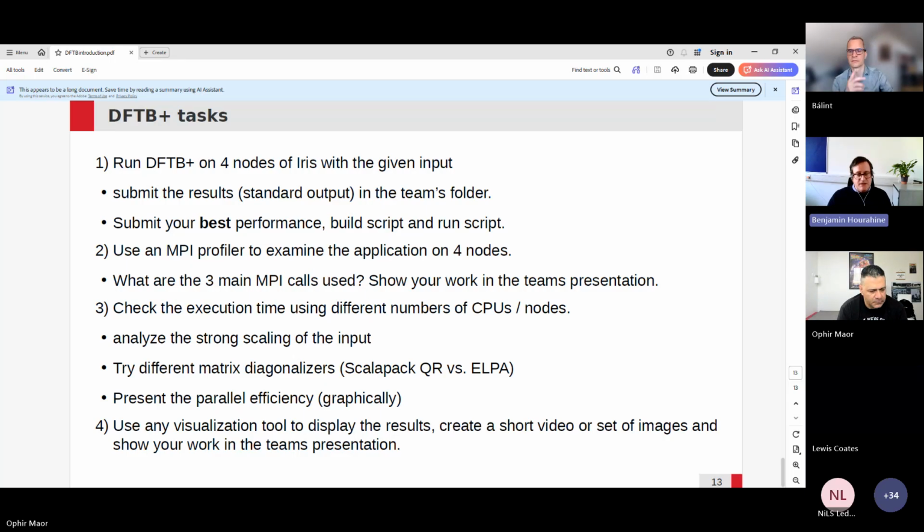There are some other settings in the input file which would change the runtime. For example, Bálint mentioned scientists sometimes changing settings for the fixed point iterations. The problem with changing those settings is that you can make the solution converge very rapidly and stop iterating, but the quality of it can be lower. So that kind of setting is possible to change, but you will potentially get the wrong answers. We're not suggesting you experiment with that part, so we put in some safe settings for converging this.